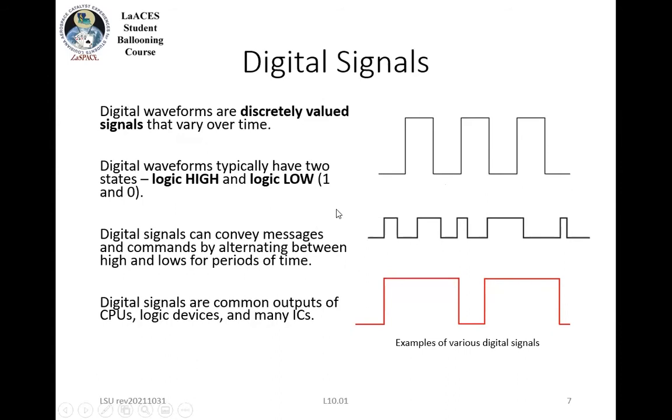And we usually use this as a way of communicating a particular signal, encoding it in the pulses here. And what's nice about these is because there's only the two possible values, you don't really have to worry too much about interference and distortion, right? If I bump one of these slightly, well, I know it's still well below the high value.